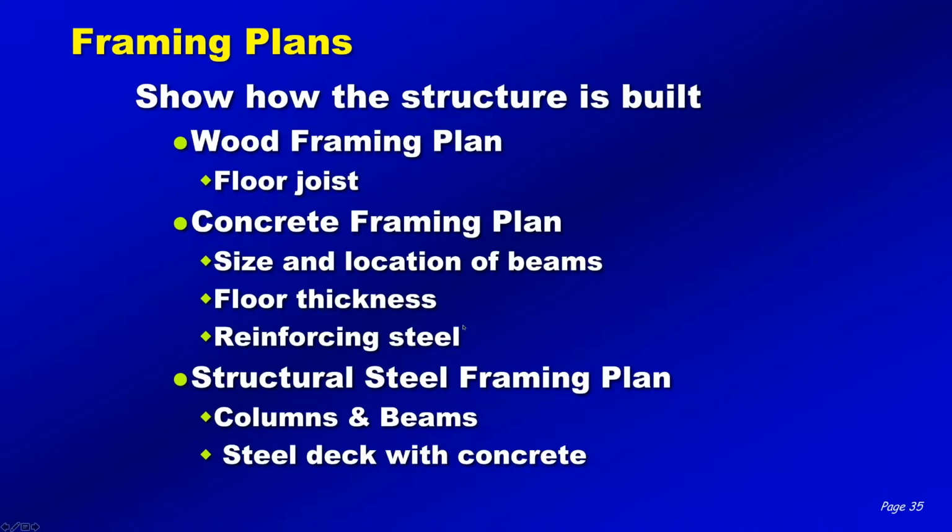When you're looking at the framing plans, obviously they're going to show you the wood, the concrete framing, the sizes and location of beams, the floors and thickness, the reinforcing steel, structural steel framing, the columns, the beams, the steel deck, all those things that are involved in building that frame to hold all the architecture.